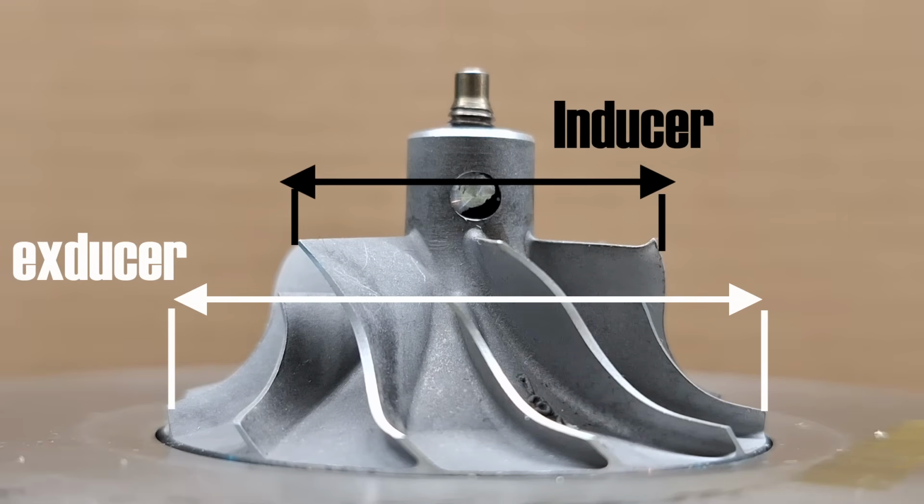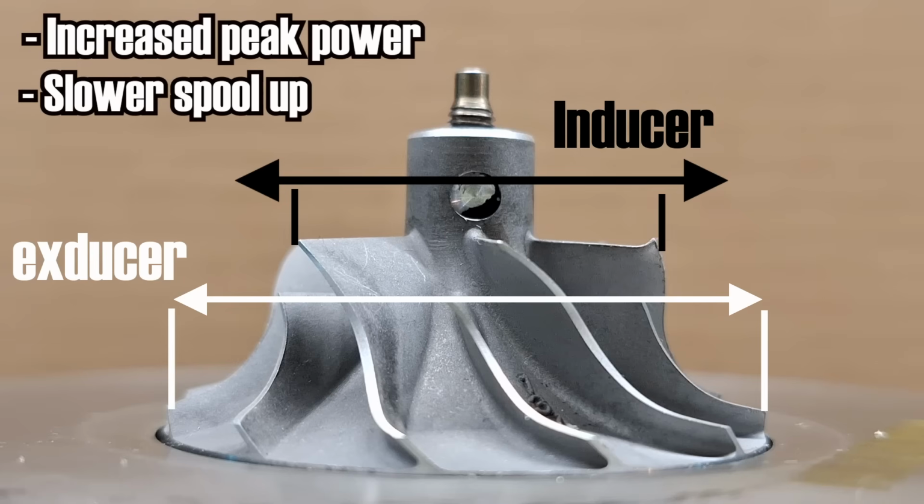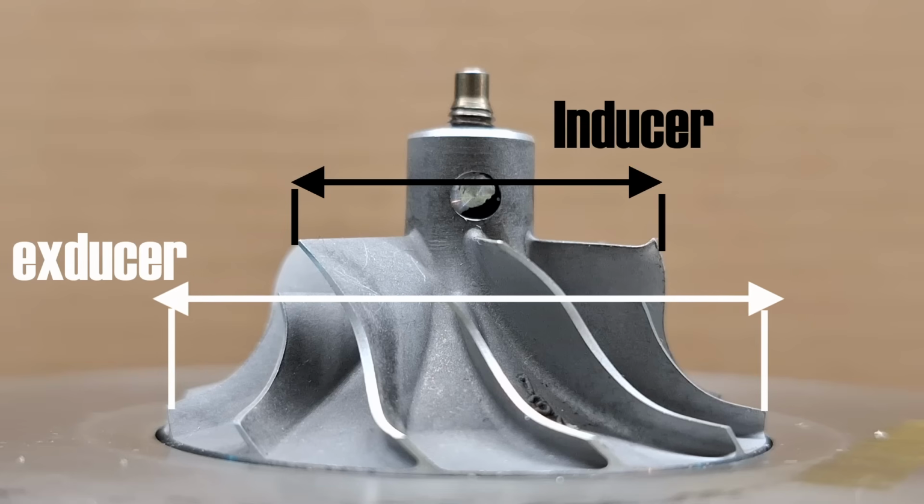Increasing the size of the inducer while keeping the exducer the same will increase the maximum potential airflow and thus peak power because it makes the compressor wheel take a bigger bite of air with every blade. The downside is that it causes the turbo to spool up a bit slower because taking larger bites of air means that there's more resistance and more work that the wheels must do. But a greater problem with overly large inducer diameters is that it can lead to surge, which can damage the turbo.